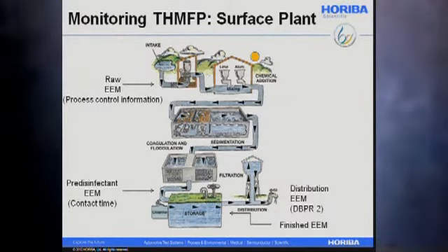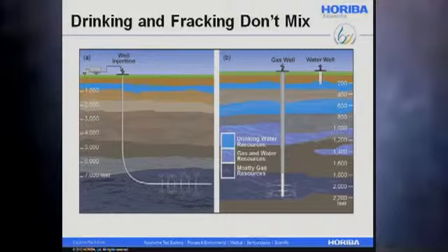Then again, they need to be able to predict how much is left and to control the contact time for the particular CDOM concentration before and after treatment. And as I mentioned before, the distribution system and the concentrations in the distribution system are something of importance. So measuring the finished water and periodically monitoring the distribution stream is basically all part of the disinfection byproducts rule.